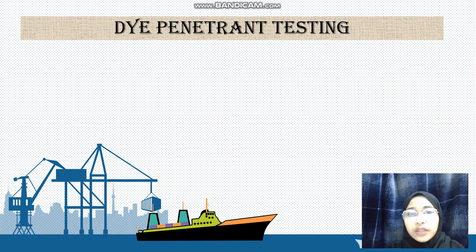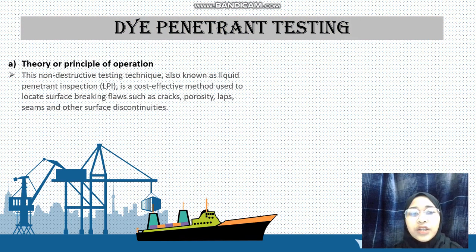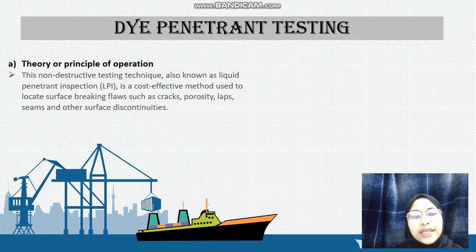Dye penetration testing is a non-destructive testing technique, also known as liquid penetrant inspection or LPI. It is a cost-effective method used to locate surface breaking flaws such as cracks, porosity, laps, seams, and other surface discontinuities.